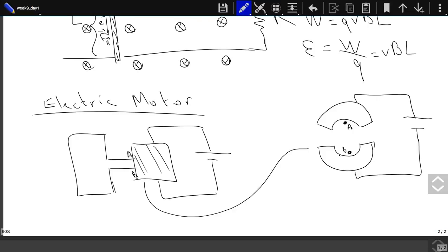When the direction of the current is changed, the angle is 180, but again the sine is 0. Well, there is only one such angle in which, with one loop, it will stay at rest. And even a very small shake will change the angle from 0 to, let's say, 0.001 degrees, and that's enough to start the rotation.